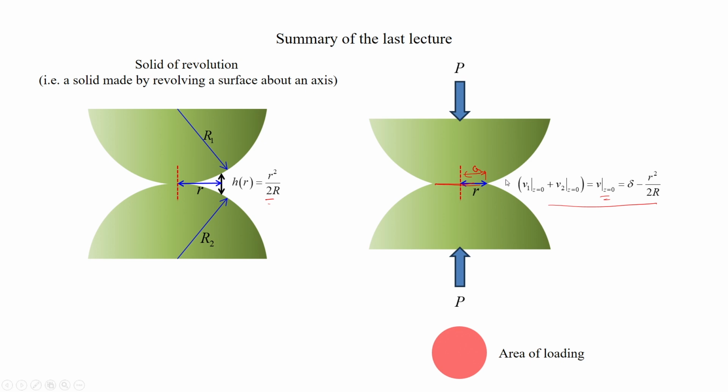So, that distance is much smaller with respect to r 1 and r 2, and this is also r, the relative radius of curvature. So, by making this assumption, what we have thought about is that this contact area is actually much smaller with respect to the dimension of these two spheres, and as a result this situation is very similar to the elastic half space that we have talked about earlier. So, the results that we have derived for elastic half space become applicable for this case.